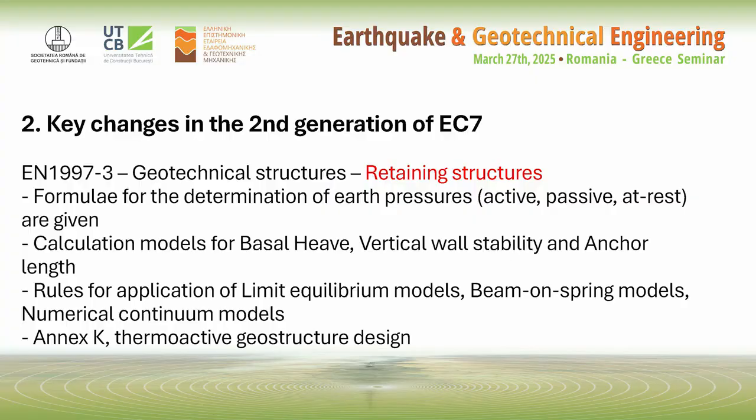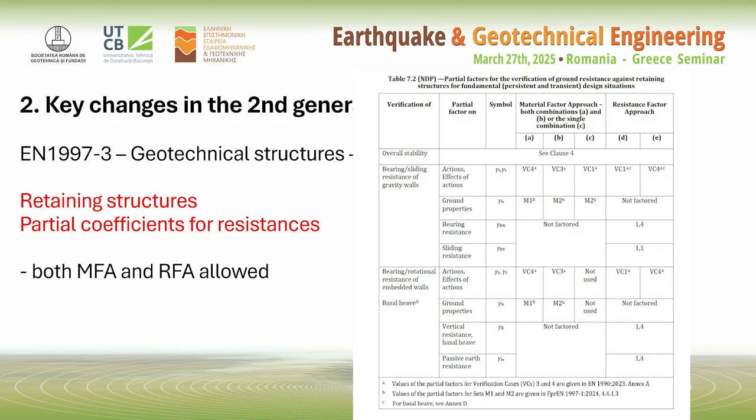For retaining structures, there are not many new things. Formulae for the determination of earth pressures, calculation models, rules for the application of the different types of models, limit equilibrium, beam on spring, or numerical continuum models, and also again the same annex about the thermoactive geostructure design. Both MFA and RFA are allowed for analyzing ULS for retaining structures.